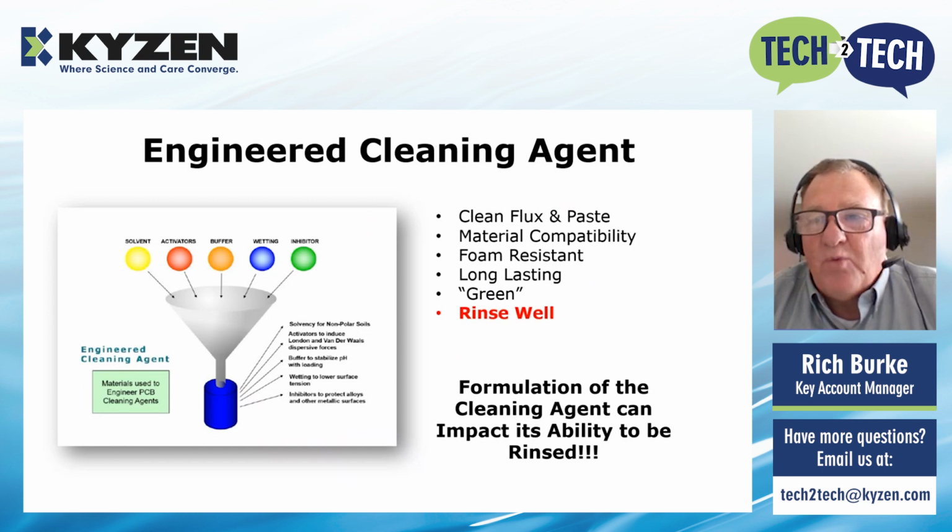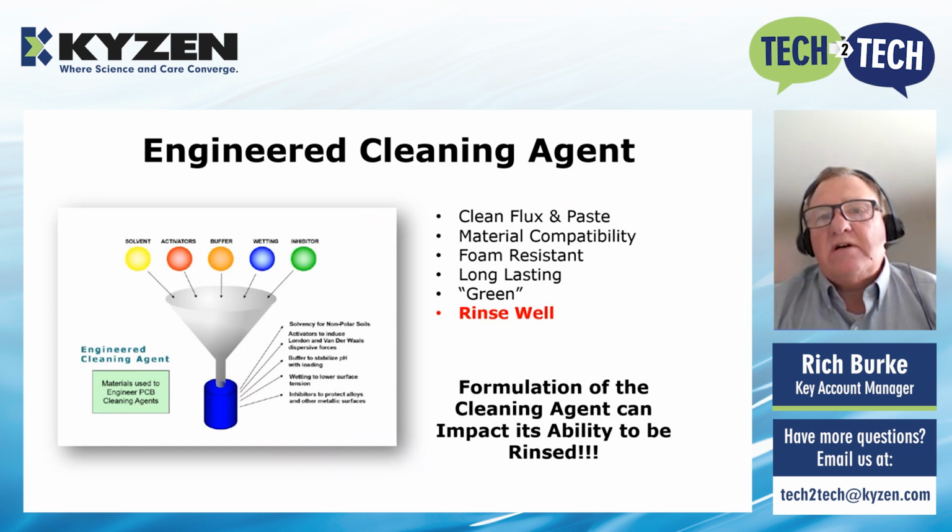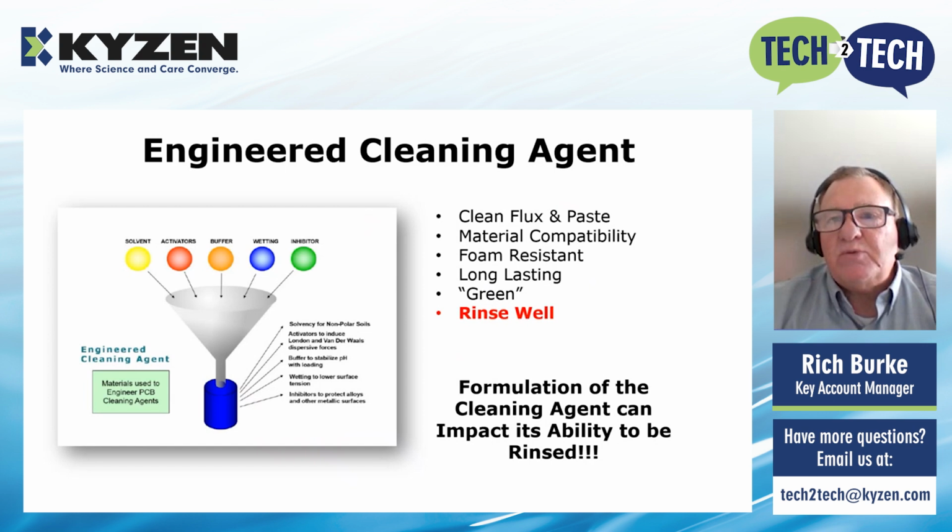The material also has to have excellent material compatibility characteristics. We want a material that is foam resistant. We don't want foaming in our wash tank, and we don't want foaming in our rinse tank. We want our bath to last long and have a large loading effect, if you will. We want our materials to be environmentally and human friendly, so green cleaning agents. And last but not least, we need a material that is designed to rinse well. So it is very important. As we're formulating these materials, all of these aspects are considered. For the purpose of this discussion, the formulation of a cleaning agent does have an impact on its ability to be rinsed.